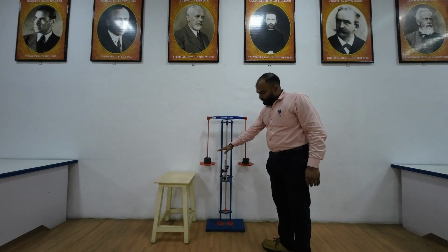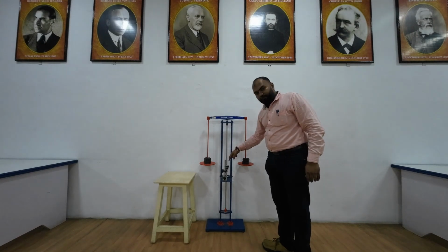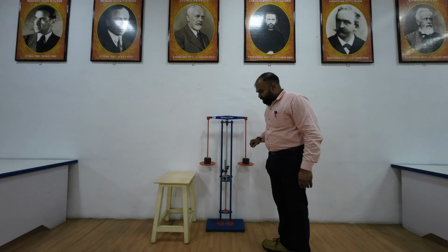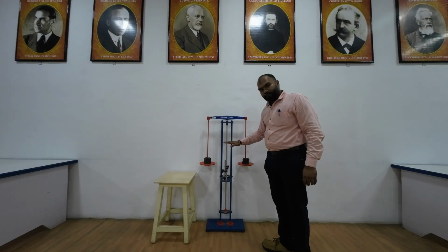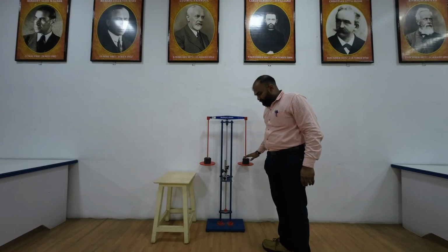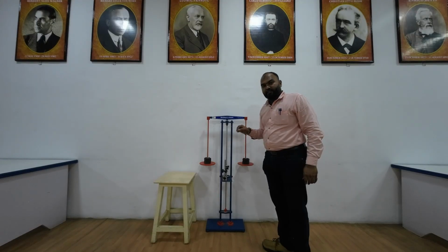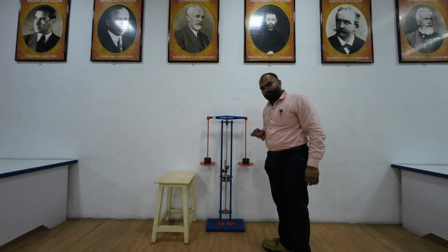We keep applying loads here. For each and every load we apply, we will be measuring the deflection from the dial gauge. We will be applying loads one by one, for example, 1 kg on both of these, and next 1 kg on both of these, and so on. So we will be able to measure deflection delta.